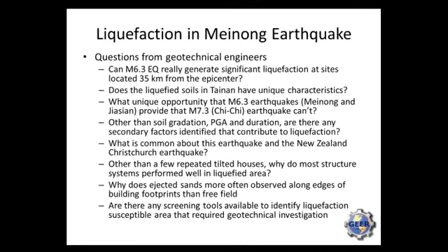Let's talk about liquefaction. Liquefaction for a geotechnical engineer, it's what we live and die for. So the question asked after this earthquake, what have you learned from the earthquake regarding liquefaction? Can a 6.3 earthquake really generate that much liquefaction at sites that are located 35 miles away from the epicenter? When I first got this news, that's what first came into my mind. And then I realized Loma Prieta, a magnitude 6.9 earthquake, caused significant liquefaction in San Francisco, which is about 70 kilometers from the epicenter. So the key thing is that the material must have a lot to do with this observation.